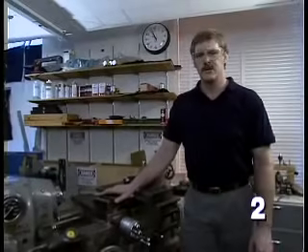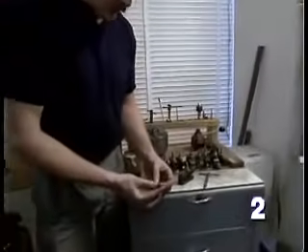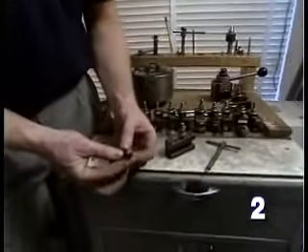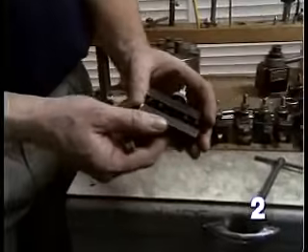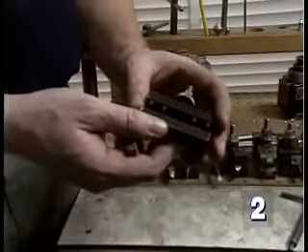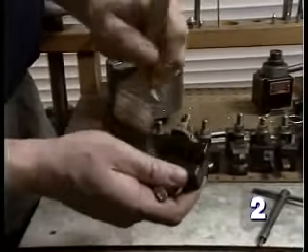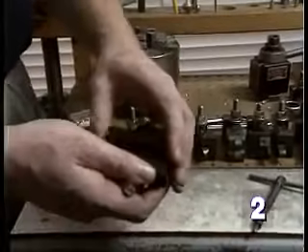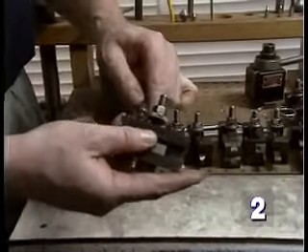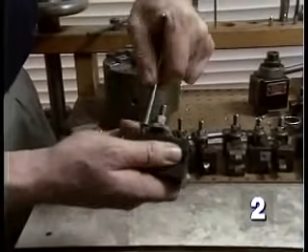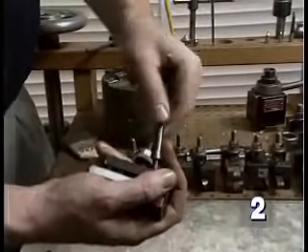Many different types of tools are commonly used on the lathe. This is a standard lathe tool. These tools are commonly held in lathe tool holders. Install the tool, making sure the tool holder is clean. Tool in place. And lock the tool down securely.